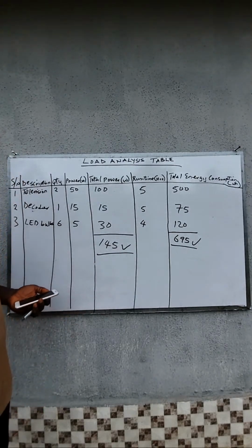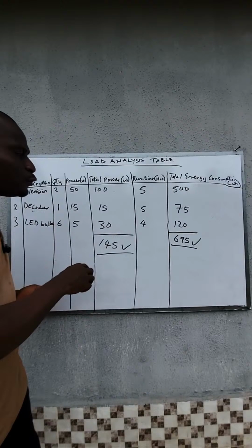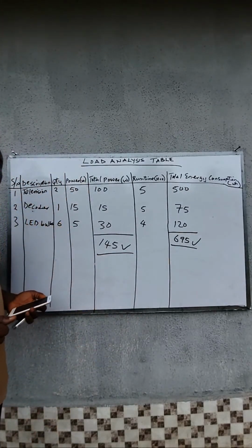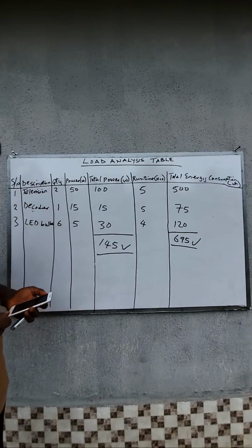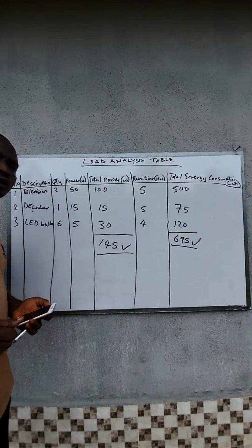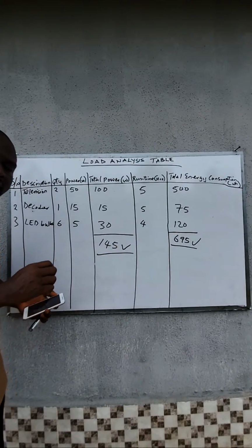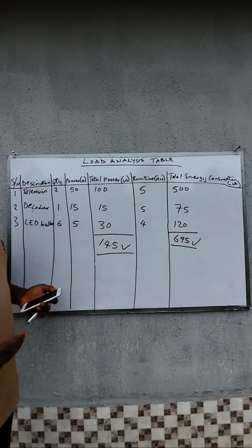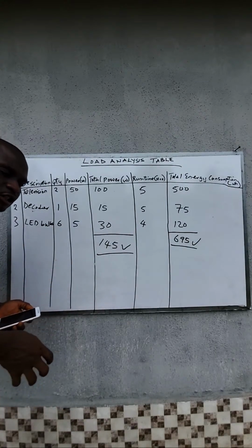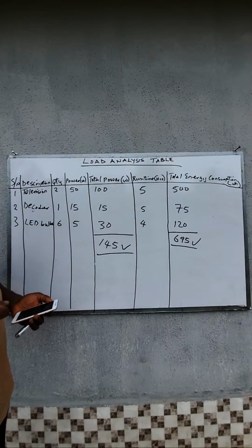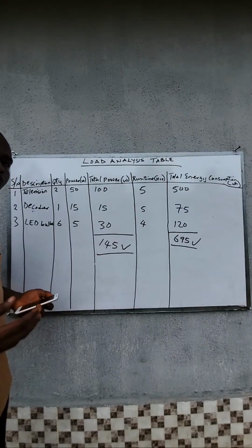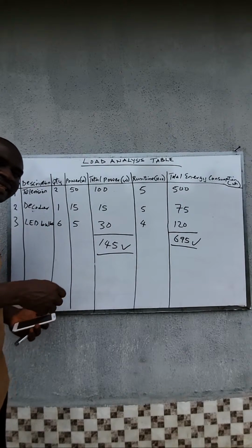So an inverter may be 3,000 watts, but it will tell you it is capable of handling a surge power or starting power of up to 6,000 watts or 6,500 watts. Now, if you go to the battery bank side, you see the high amount of current that load is drawing. If your battery bank is not able to withstand that current in those few seconds, the battery bank will also fail. The inverter will sense low voltage, because as it's trying to draw that power, the battery bank cannot supply that energy, that starting current.